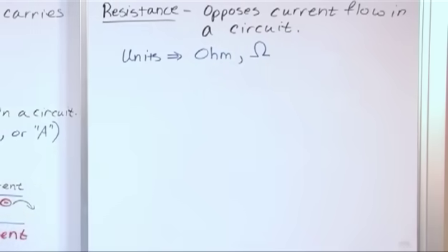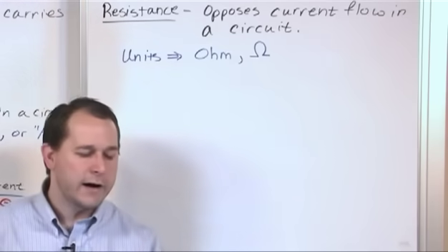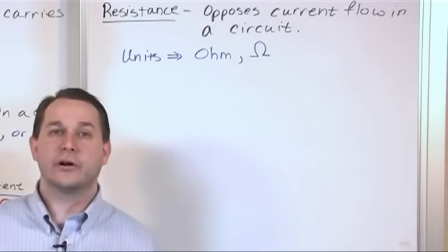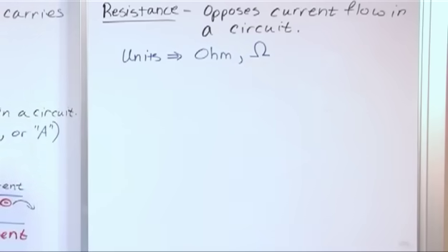So, very, very important topics. Current is the flow of electricity. Voltage is how much push you are pushing to make this current flow. And you're always flowing through something. That something is always going to have a resistance. Different size wire, different resistors, different circuit components are going to manifest themselves as different values of however many ohms.